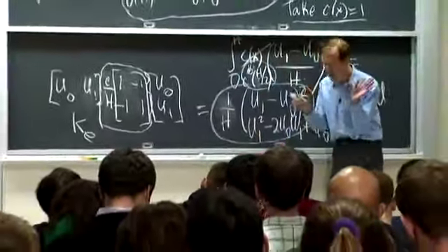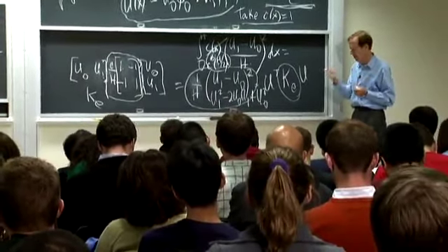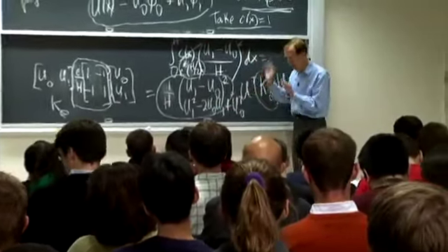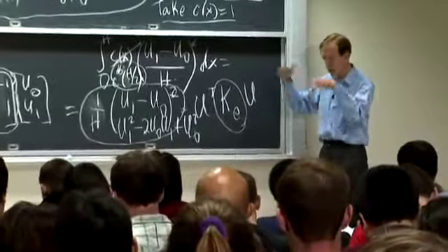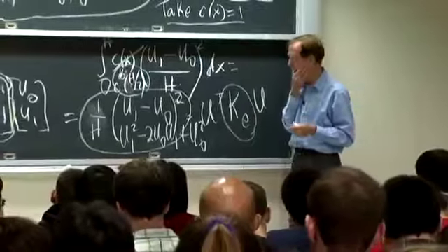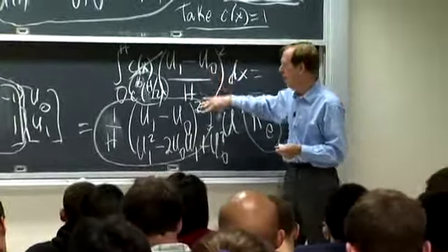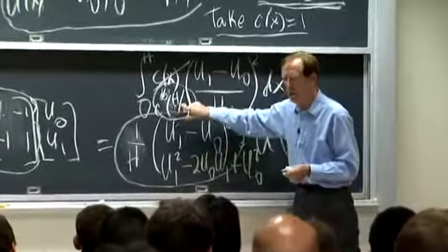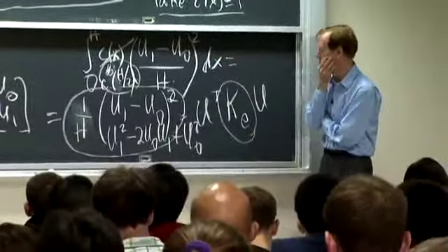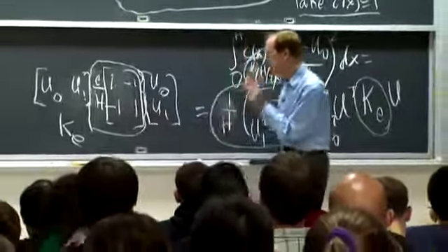Numerical integration is one part of the picture that we won't go into all the different rules. There's a rectangle rule, there's a trapezoid rule, very good. There's Simpson's rule, that's better. As I get higher order elements like those cubic elements I spoke about, the numerical integration has to keep up. If I was integrating cubic stuff, I wouldn't use such a cheap rule. I would go up to Simpson's rule or Gauss's rule or somebody's rule. Anyway, that's the C part. Here's the part that stamps into the matrix.